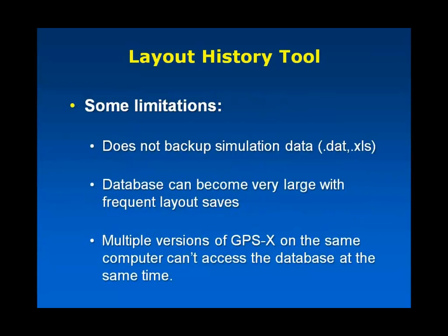There are some limitations at the moment. It only backs up the layout files themselves. It doesn't back up the data that goes with it, if you have a lot of data being read in. It's a database, so it's going to grow in size as you use it more. It's actually a fairly efficient database, so it doesn't take up a lot of space, but it can if you make a large number of saves over time. And right now, multiple versions of GPSX being used at the same time on the same computer can't access the database together. But in general, it's a useful feature, and I've been using it since version 6.1 came out last year.